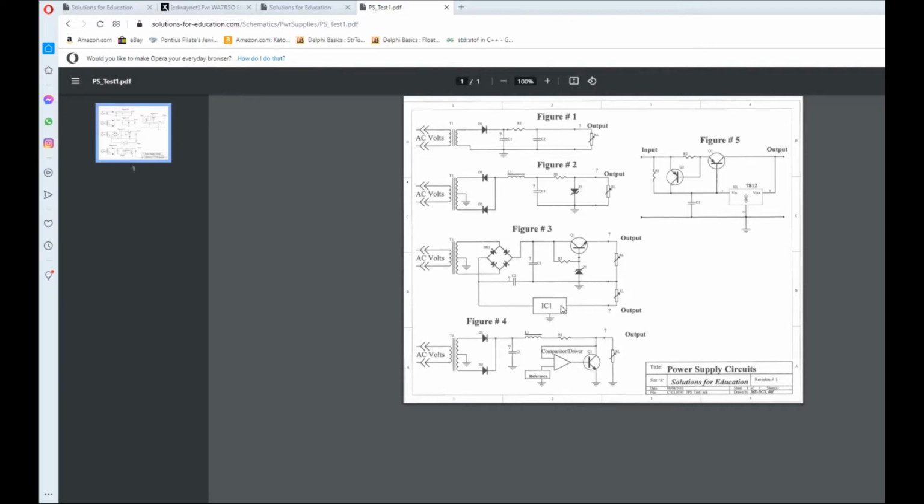What is this IC1? This IC1, if you were wanting, for instance, a 5-volt power supply, this would give you your 5 volts up here, but it might be 12 volts. Down here, you might want 5, or you might want a negative 12. That's what this guy is. Quite commonly, there is what they call a 7812 or a 7912. A 7812 is a positive voltage regulator. It's a 3-terminal device and very, very popular in a lot of circuits, and so it's well known.